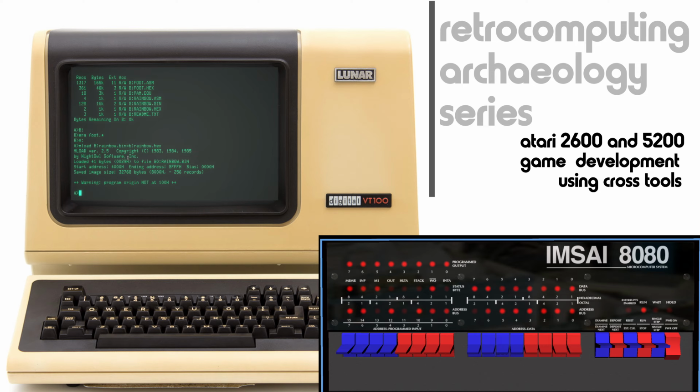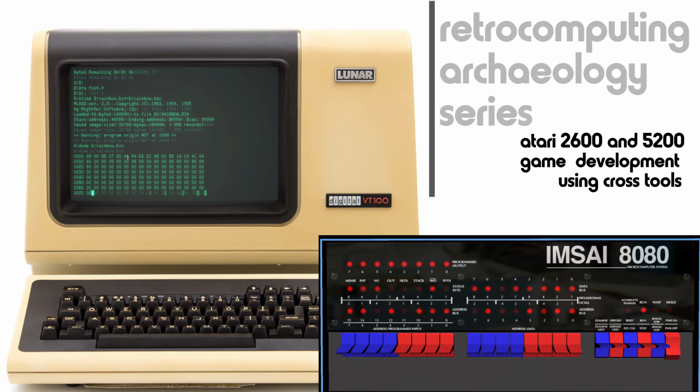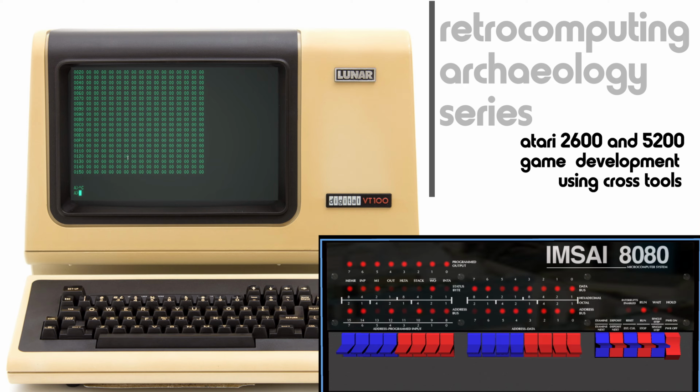And if we do a dump on this, we can see that it's our program right here with a lot of empty space in between, but it's here nonetheless. Looks good to me. And we can see that it created, as part of the assembly process, the hex file for our little demonstration program.